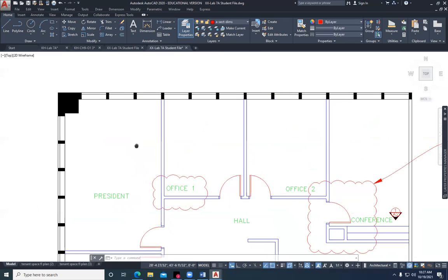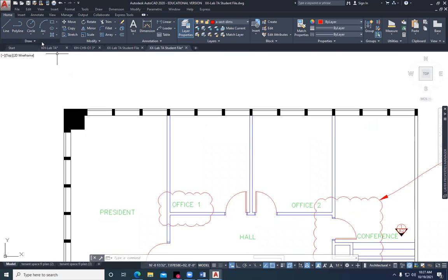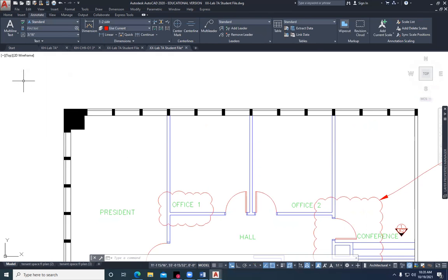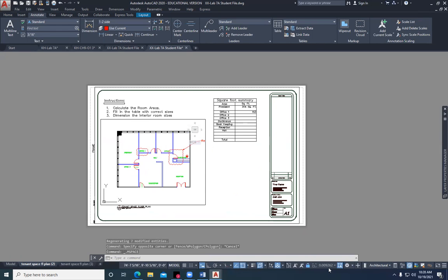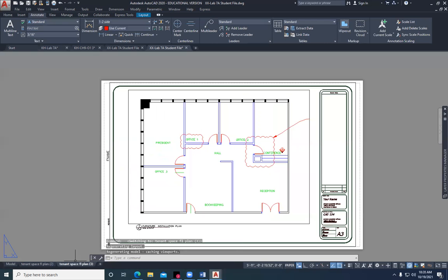So as we're looking at dimension styles, what we're talking about here would be under the annotation tab. And then as you work with your dimension styles and your dimensioning in the scale factors, the easiest way to work with dimension styles, and I think we ought to just show them how to do it in Paperspace, don't you think, Al? Fantastic idea. Is while you're in Paperspace, you go into the viewport and you need to set up the viewport for the proper scale. So I'm going to just go to a separate page of it. And so I have a bigger viewport here.